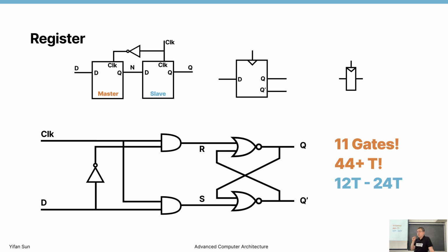In extreme cases, we can reduce it down to a very few transistors, probably 3 transistors in the most extreme case. But that is a very special one, a DRAM-style design. For most of the time, the smallest cell without the reading and writing logic is typically considered 6 transistors.